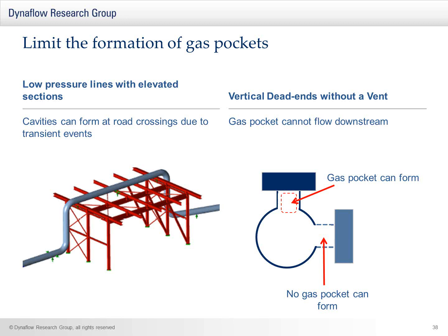Whilst with the dead ends without a vent, for example, that's shown in case 3, where the fiberglass T totally failed, it will be much more beneficial in that case to have the T connection in the horizontal direction rather than the vertical direction, as then no gas pocket would be able to form, as the gas would not accumulate at the highest elevation.